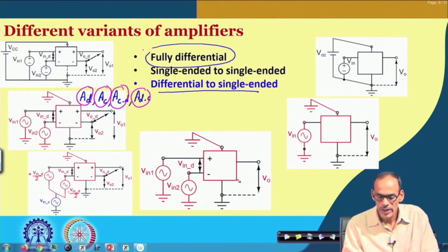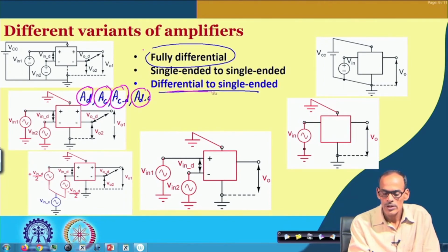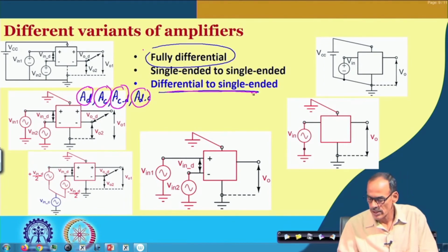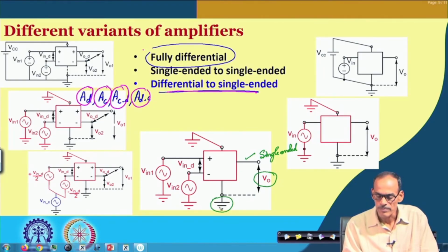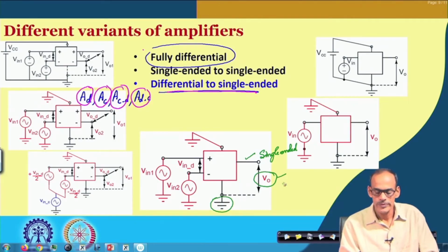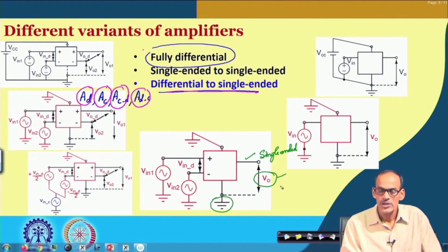Now, on the other hand, whenever you are talking about the differential to single ended amplifier, since the output port is single ended, the signal is with respect to ground. So, there is no separation of the common mode and differential part of this signal.